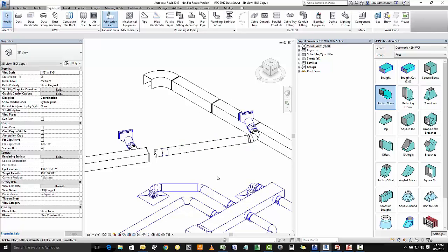In 2016, however, you would have to go to building3dcontent.com in order to access the entire fab database from Autodesk. It's all up there for you to download and use. Then, if you don't have fab on your computer, you would have to install a trial of the fabrication software to be able to load the fabrication parts into Revit for you to use in 2016.